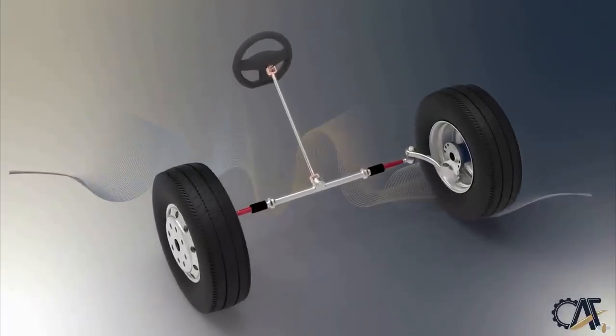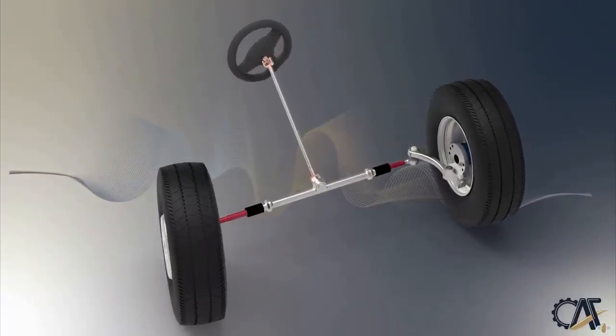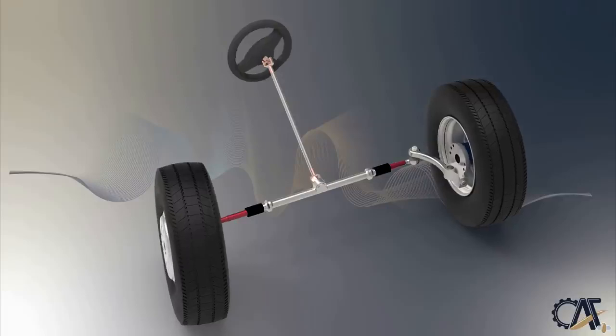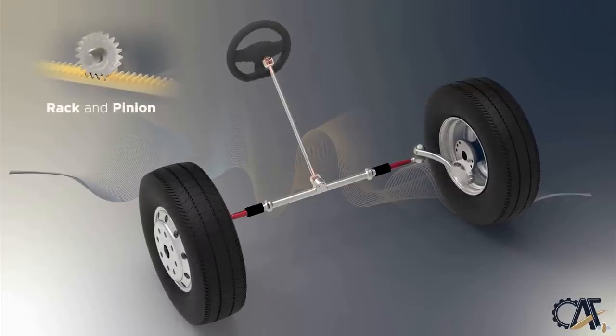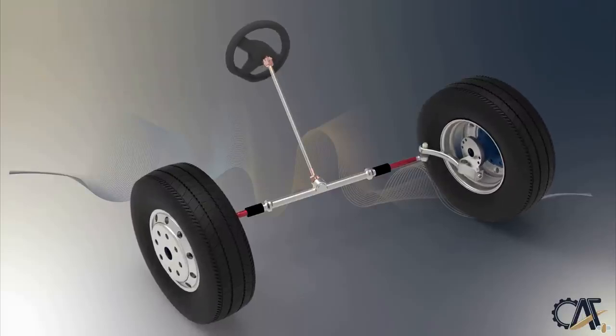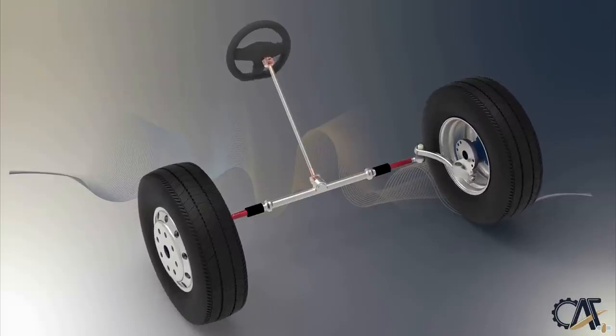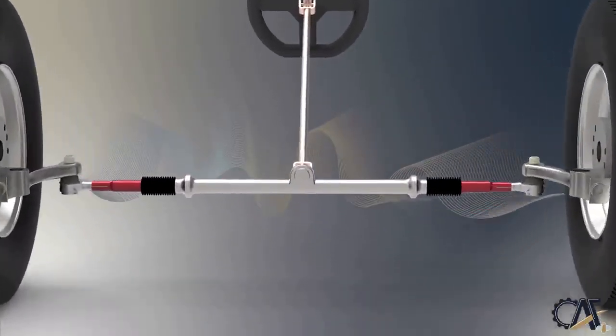Next up, let's take a look at an example most people interact with on a daily basis: the steering wheel of a car. The steering wheel assembly primarily controls the direction of a vehicle. But what type of gear enables this motion? The rack and pinion is a type of steering mechanism with a pair of gears that convert the rotary motion into linear motion. This system consists of a circular gear called pinion that engages with the teeth on the linear gear shaft called the rack.